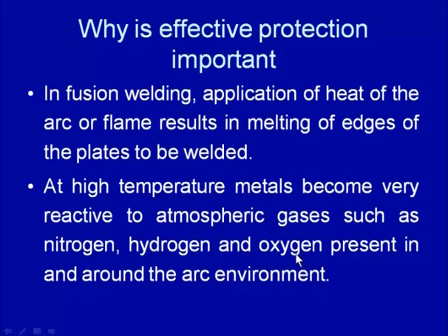So, at high temperature, because of the high reactivity of the molten weld pool with atmospheric gases such as nitrogen, hydrogen and oxygen present in the arc environment, if proper protection is not given to the weld pool, then these gases will react and form oxides, nitrides and hydrides, which will act as inclusions, and these inclusions will deteriorate the mechanical performance of the weld joint.